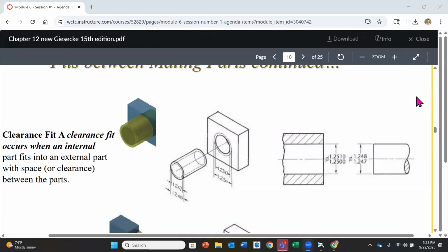It's a typical drill size, exactly. That's taking the manufacturing process, how we're going to make that feature, in this case a hole. We want to make sure that we have the nominal size on that hole size, because that's a typical drill. That's something we would have available to us. It wouldn't be any special tooling that we would have to order, which would cost more money.